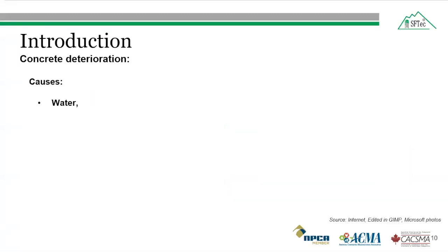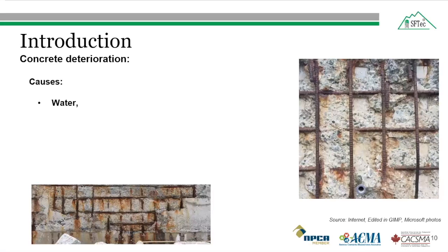Water exposure can rust the steel particles in the concrete and rust the reinforcing bar in the reinforced concrete structure. Rusted steel can expand up to 4 times its normal size, causing concrete to break apart. The red streaks on the concrete surfaces are a sign of rust. Concrete corrosion is a result of salt water exposure or sulfur in the environment. The deposit of salt from winter roads can accelerate concrete deterioration.